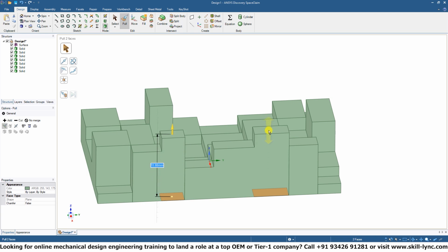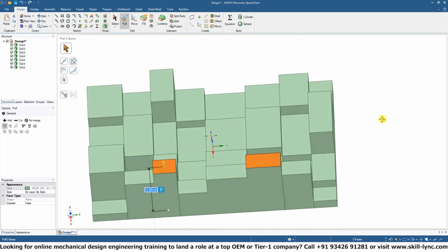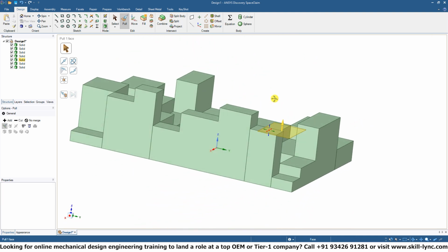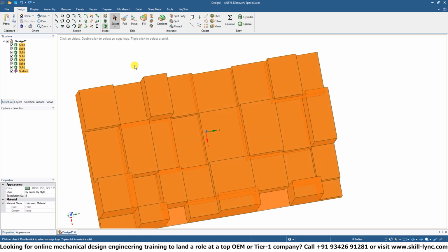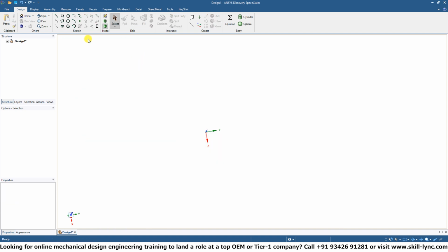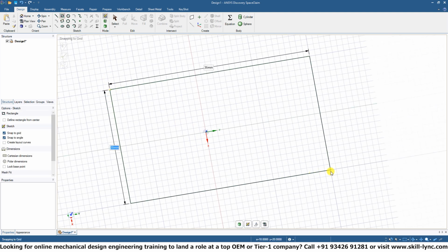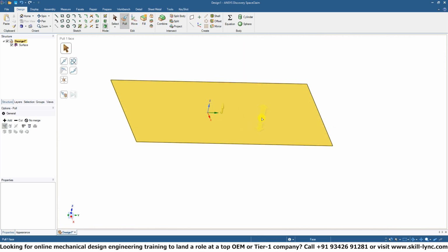And as you can see, within a matter of minutes, we've created some relatively interesting geometry over here. A multi-leveled structure. That's just one example of using the pull tool on a multiple area sketch. However, let's say that we're more interested in creating holes or negatively extruding or cutting geometry out.